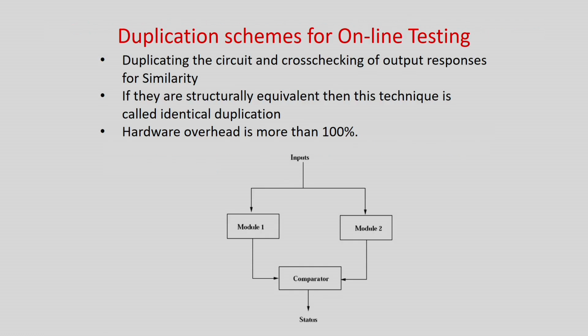We will see how another group of researchers handles online testing, and their main emphasis is to keep the circuit intact. I am not going to change your original circuit, maybe slight changes, but very minimal. But of course there cannot be any magic. So these people involve more area overhead compared to the bidirectional error detecting code theory. The best advantage of error detecting codes for online testing is the low area overhead. That is very important, and test coverage is very high.